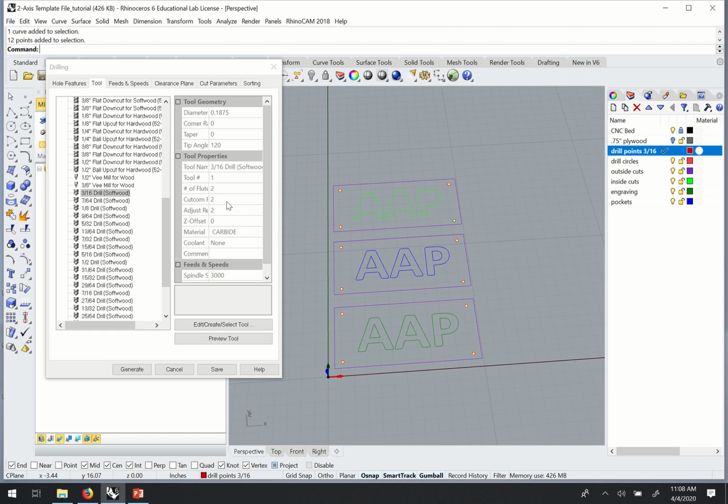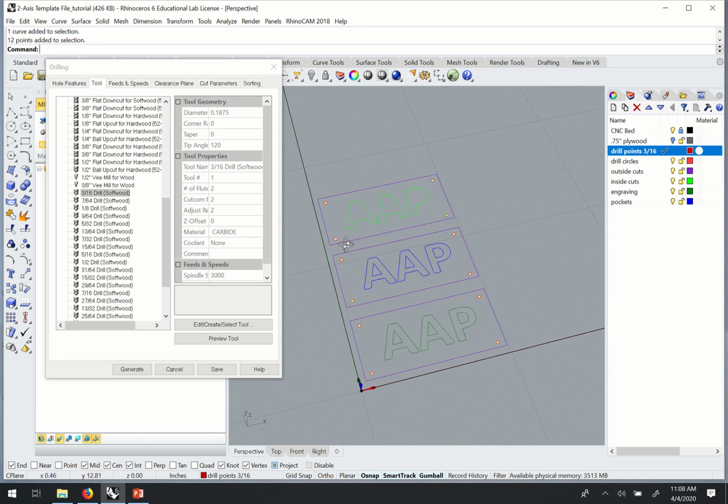I talked about order of operations, and that translates to the physical setup of the CNC machine. The CNC can have multiple tools for each different operation. It can have up to 5 tools, and each one of those has an individual tool holder. The way we identify those tools is with a number, 1 through 5.